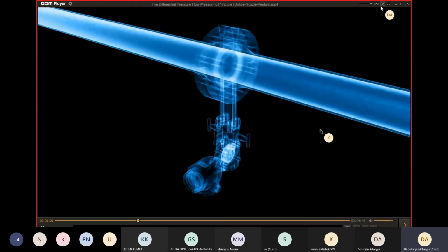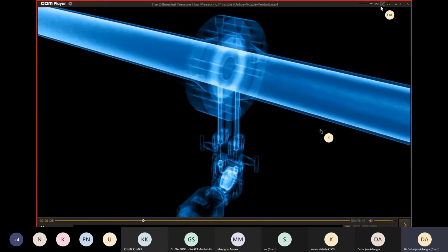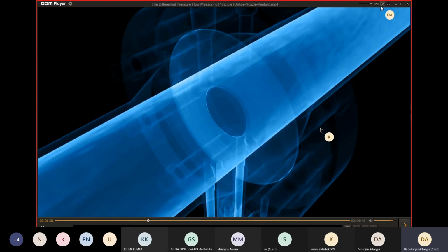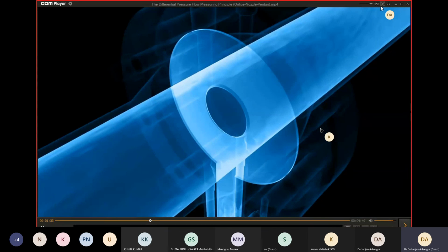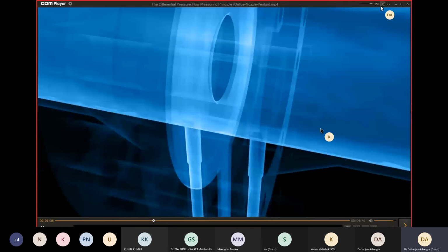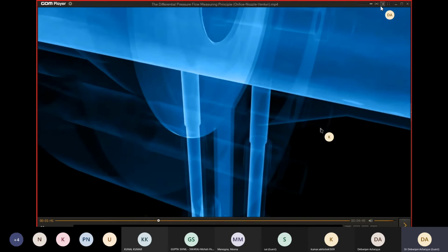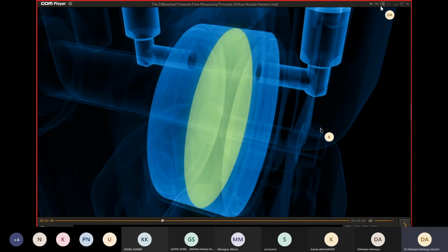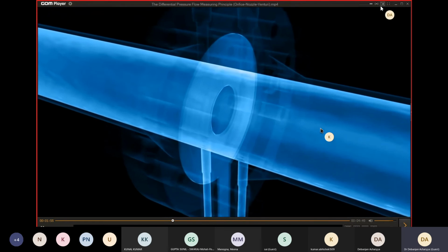Here is how this measurement method works. Differential pressure flow meters have an artificial restriction integrated into the measuring tube, illustrated here by the example of an orifice plate. Two holes are located in the pipe wall, one before and one after the orifice plate. Two separate tubes connect these holes to a differential pressure sensor with its two pressure chambers separated by a diaphragm. The tiniest pressure differences in the flowing fluid can be precisely measured.